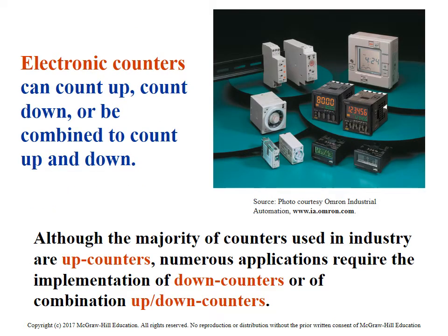Here are some digital counters, things that you may or may not run into in industry. Some of these components you'll see in a DIN rail mount type connection, or even mounted through a cut hole in a control panel, where you'll be able to see the display. You can set these up so that when they reach a certain count, it closes a contact, so you can use different outputs. Maybe even an Ethernet cord plugs into it that translates that information to some other device that lets it know what count it's at and how close it is to the end, that kind of stuff.